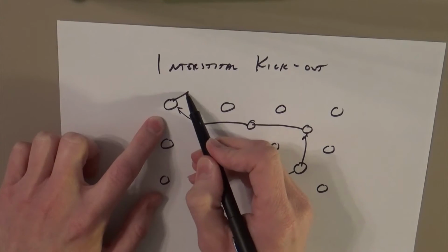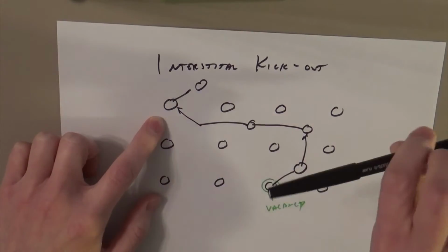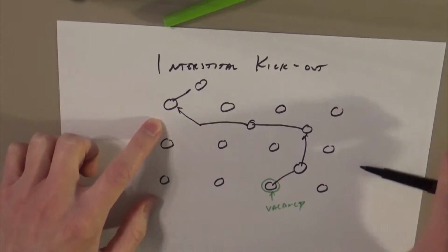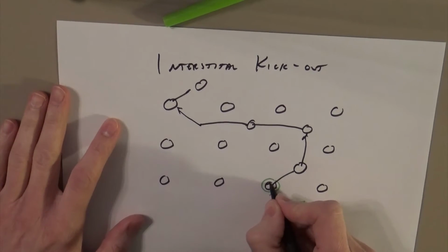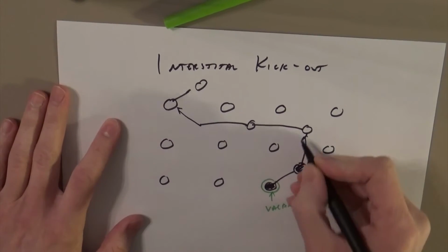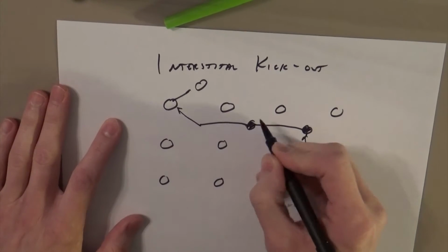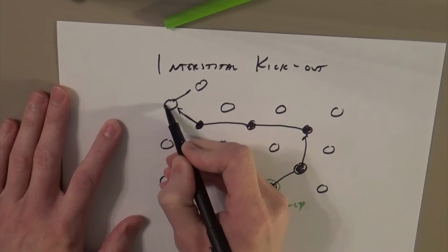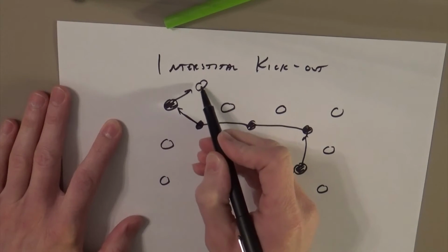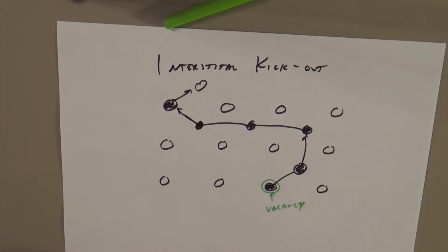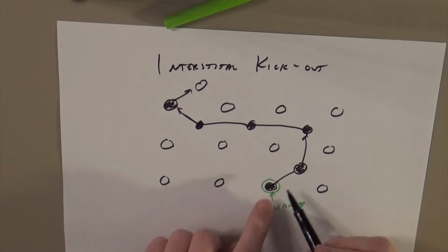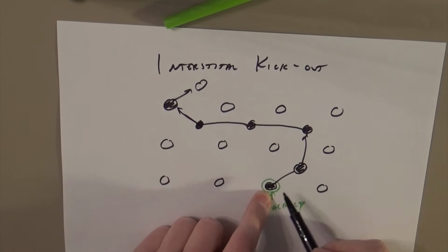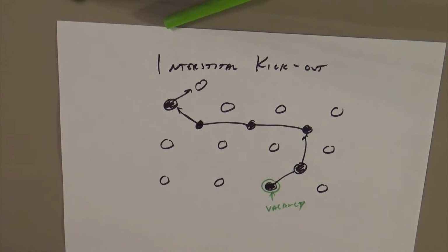So this atom now hops to the interstitial site. And this atom, which I'm going to label as a filled-in atom, is going to hop into this site, and this new atom is now diffusing. So it's kind of site to site, but there's this interstitial mechanism which allows for enhanced diffusion.